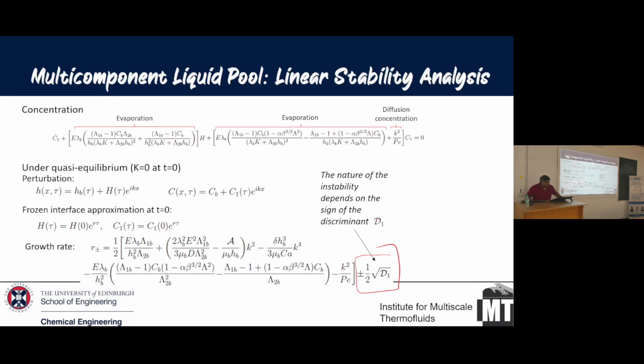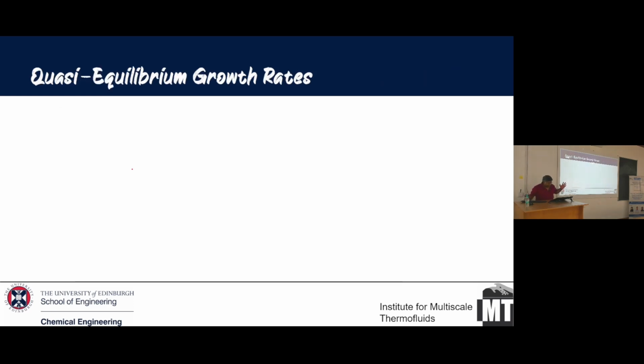If you remember, we had a case. We assumed that there is an equilibrium constant called k, and when we set k equal to 0, it actually is a fake case where we say that the temperature across the interface is constant and equal to the bulk of the liquid. So essentially, you have very slow evaporation, but that is a very special case. Technically, we never have quasi-equilibrium.